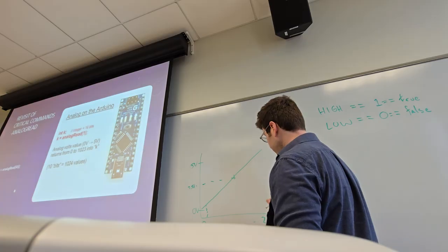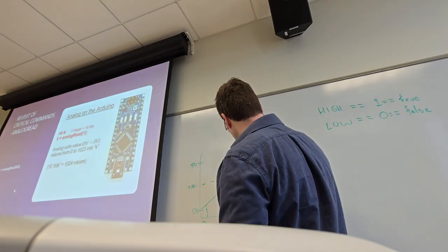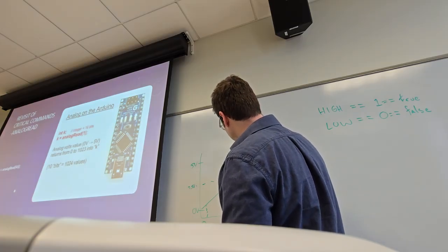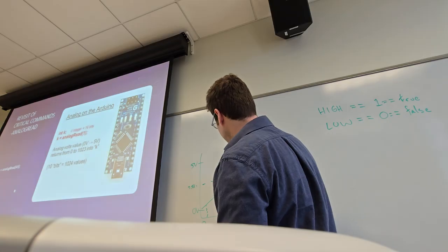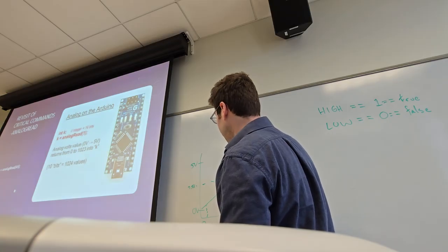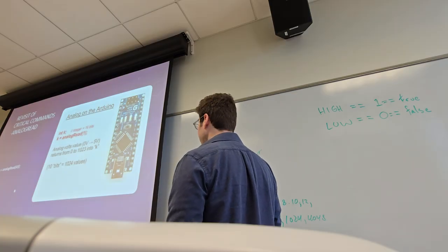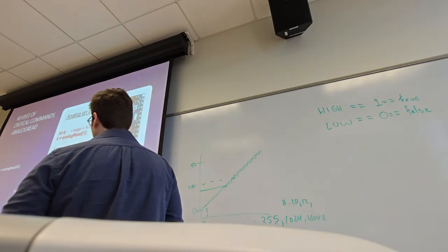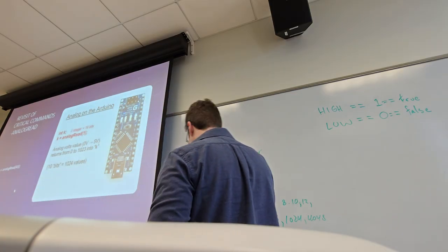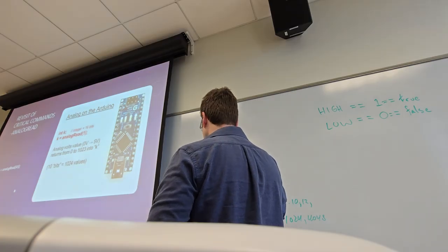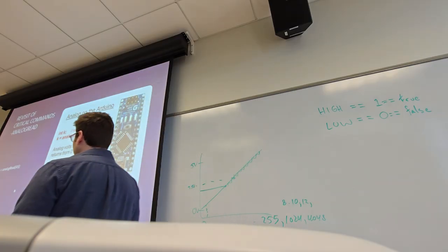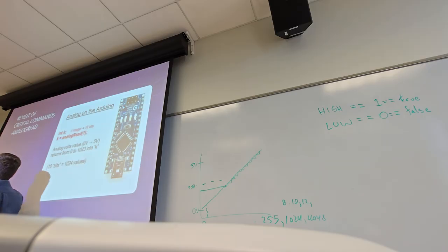Often this scale is chunked up into the smallest changes that we can discern from one step to the other, and then we just count those steps to get to a point. The number of steps between 0 and our point is stored in our variable when we call analogRead.